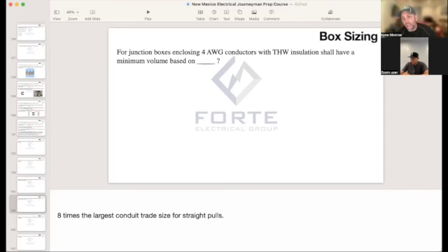That'll give you how many 15 amp circuits you need. Now, if they were asking for 20 amp circuits, you just divide by 20 instead of 15. But since they're asking for lighting loads, those are 15 amp circuits. So that's how you do that one.